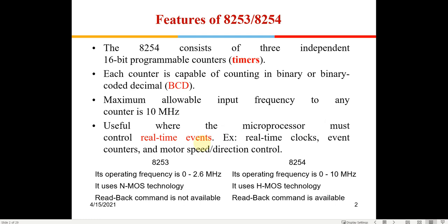When we learnt about delays, we learned that we write a small program to insert delays, like for controlling motors and things like that. But when we insert delays within an 8086 program, the microprocessor has to execute that program to create that amount of delay, and it cannot do any other function during that time, right? So that is a mere wastage of the 8086 resources.